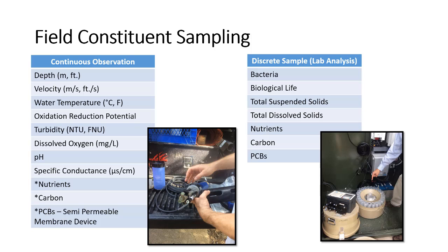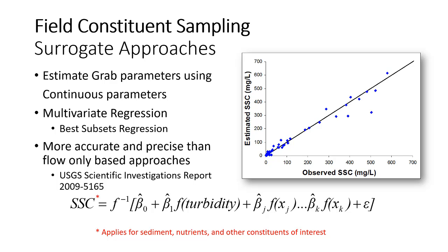Okay, so with these discrete samples, we typically are measuring concentrations, right? With these, a lot of times we're not even measuring concentrations. Like the NTU, it's not a concentration. It's just a random unit, right? So when we measure this turbidity, typically what we're trying to get at is something like total suspended solids or total solids. So what typically is done is that a relationship curve is developed such that we can measure, let's say, turbidity real time at really short time intervals, and based on grab samples that we've taken that we've related with turbidity measurements, we can develop a rating curve, right?